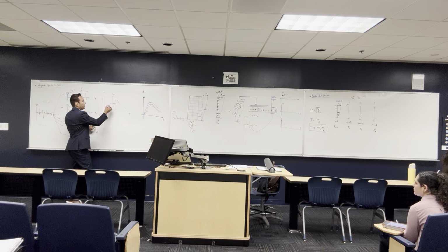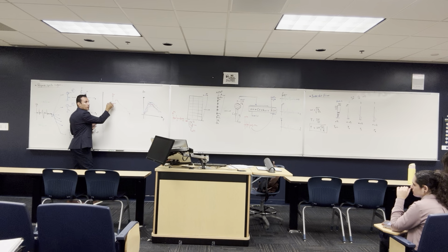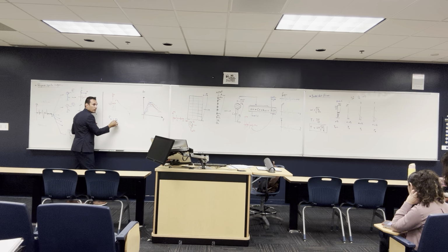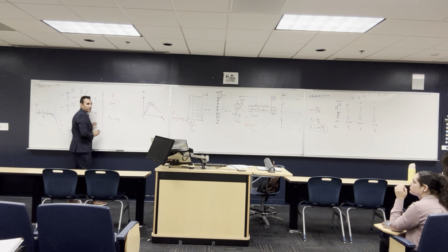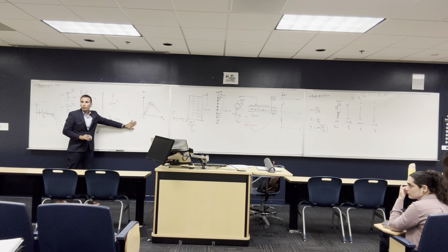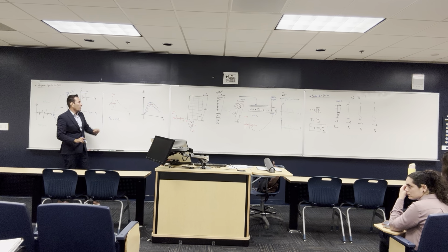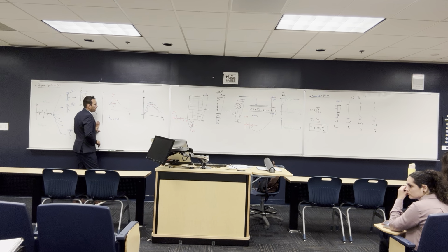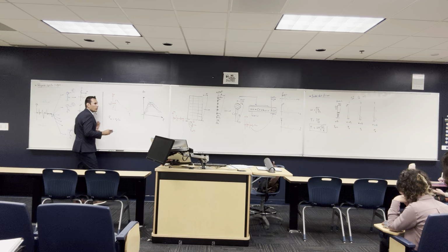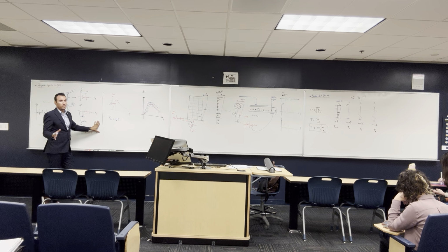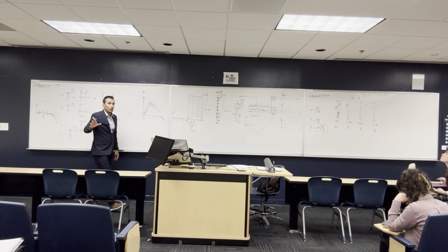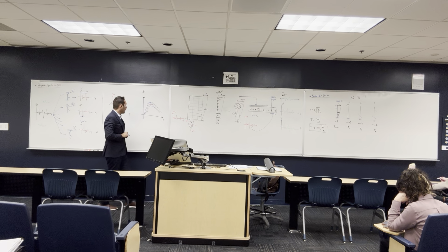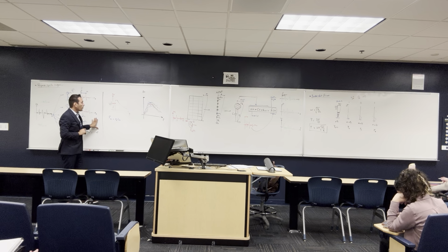You get the SA, the acceleration of the structure, then you get the F base by multiplying the mass of the structure by SA. There's many factors here, like the importance factor, but I'm not gonna put them. And when we use the mass, we use something called the effective mass. We don't assume that all the live load is within the building. We assume maybe 0.5% or 0.25% of the live load. So that's what we put here.